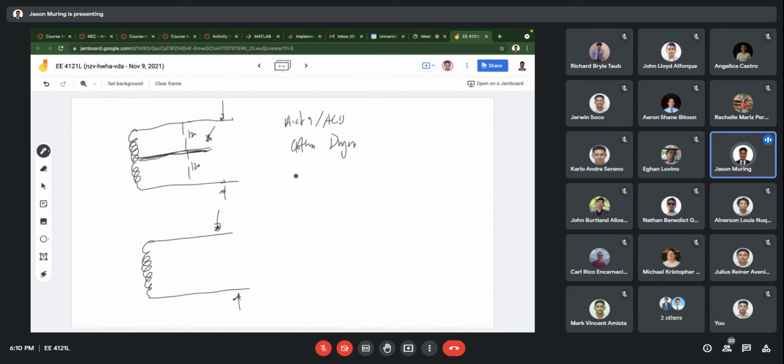Then we also have a range. Say these two are using 120 volts, and the range is 240 volts. Therefore, the range should be connected from phase to phase, so there's no problem here. It will not affect your neutral load. So when you calculate your neutral load, this should be omitted, but for the calculation of the line conductors, it applies.